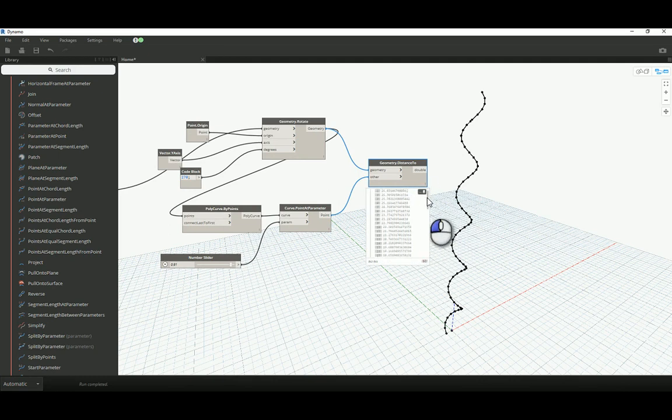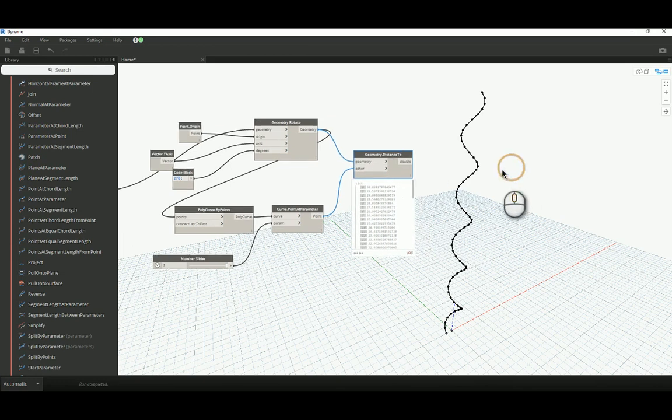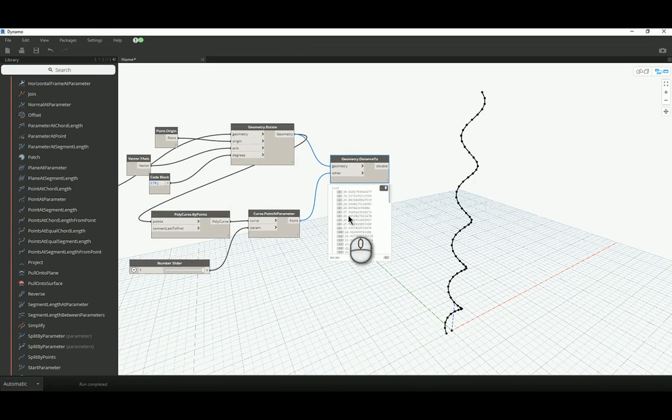If I take a look at this information here at the moment, I see that I just have a list of values. Okay, this might not make a lot of sense at the moment. Basically, these values are the distance from that attractor point that's moving to each and every other point in this entire shape that I have here. Okay, now what I want to do with this is use these values to define the radius of a bunch of spheres that I want to place at every single point over here.